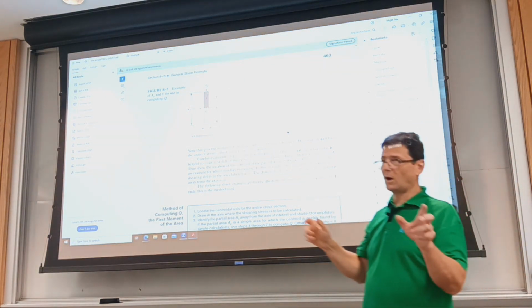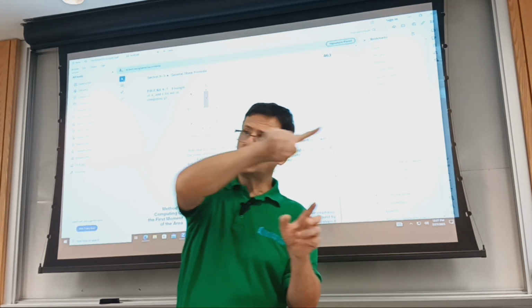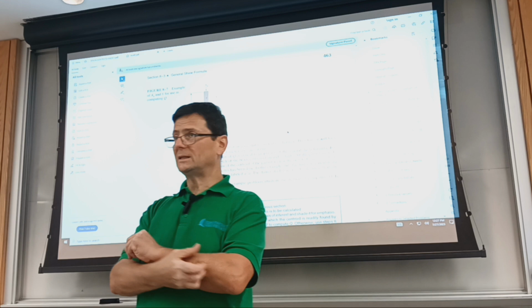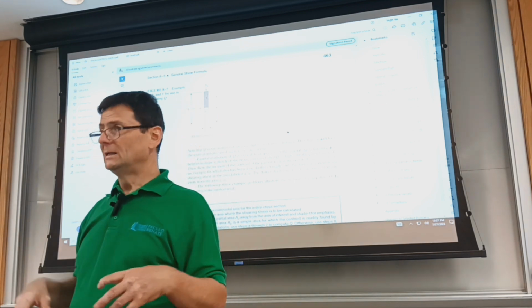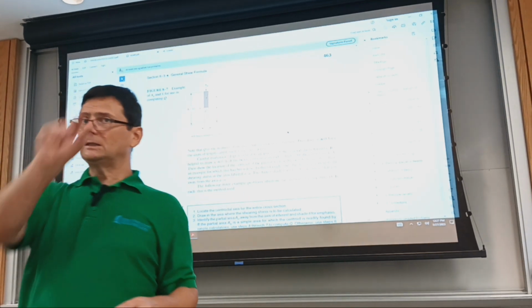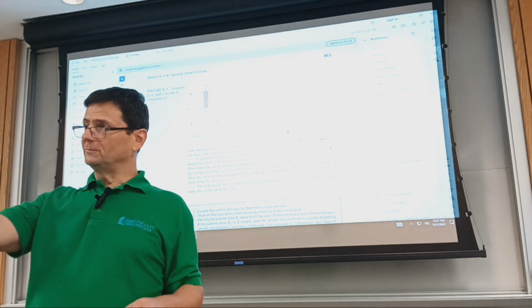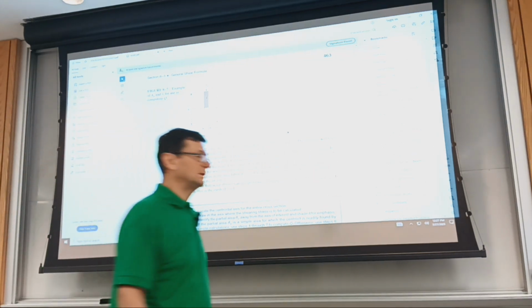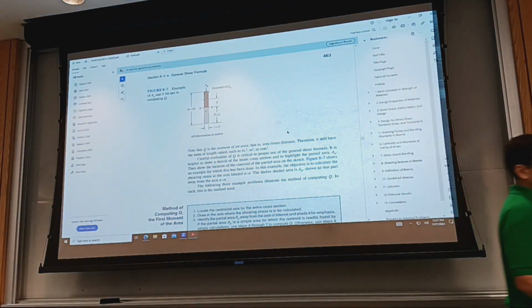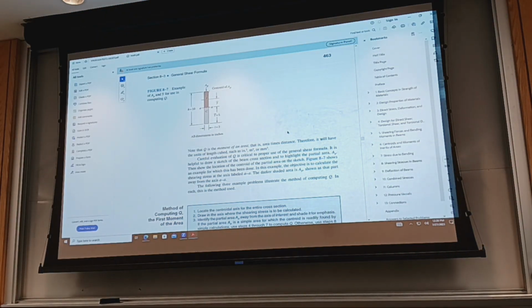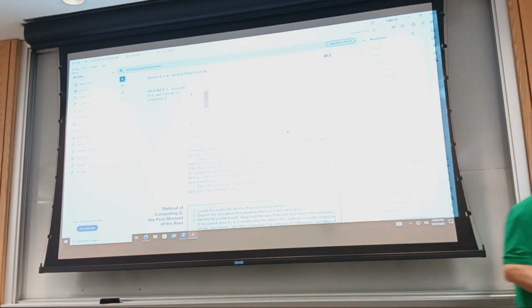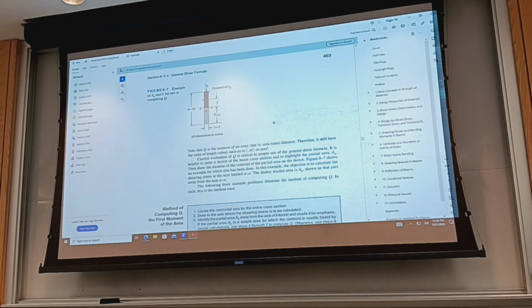Oftentimes they have one continuous weld, which takes forever to perform and unnecessarily strengthens the joining. You can do a 1 inch weld and then nothing, and after 5 inches you do another inch. It's called discontinuous welding, and it's commonly done in practice. The only issue is it does not provide water tightness, so if that's an issue, you need to maybe seal that area somewhere.